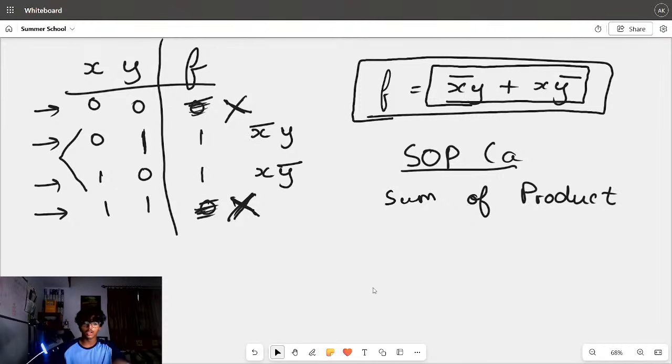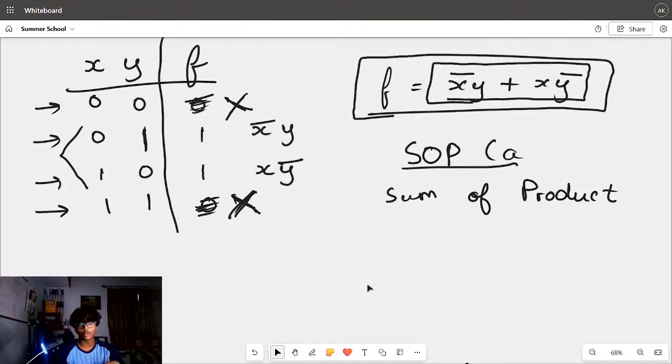Now, don't cares come in handy when you're trying to simplify the circuit, and I'll tell you how to later. When you're trying to simplify the circuit, sometimes it helps to not care about certain cases. It simplifies the circuit more in that case. So that is why don't cares are very essential. If you assume that some cases in your truth table aren't really going to happen in the real world, then you can use a don't care and you can make your circuit so much simpler.